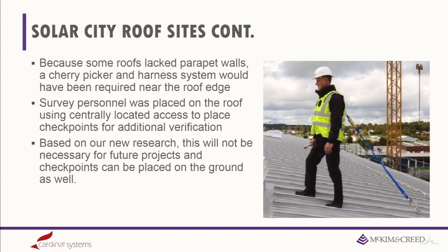But the additional benefit of this approach, when we first did this, we did put people on the roof because we wanted verification on top of the roof that the information we were collecting was accurate, since all of our control was on the ground and not on the roof. And indeed it was. Based on our testing, we found that features that are really close to the camera tended to be just as accurate as the features on the ground, actually more accurate, which shows that our internal orientation, our camera model, was holding quite well.